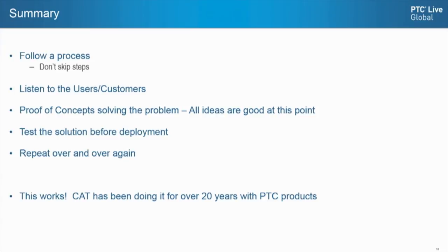It depends on the supplier. You said PPAP, but it's the same naming convention with us too. Before they build, sometimes they'll show us their image of the form board drawing just to make sure they've made the form board drawing to where we think the breakout should be, and that it's dimensionally right. But finally, when they deliver the first piece, then we'll use the engineering drawing. The engineering drawing is the key. It's what the PO is calling out and everything else. So that's what they're held to, that engineering drawing.